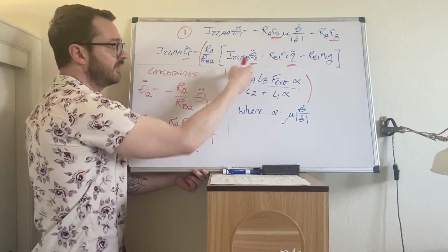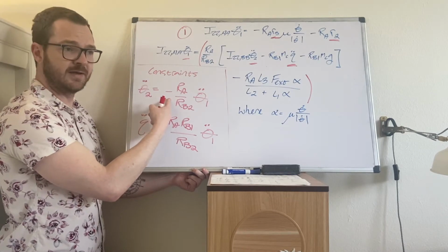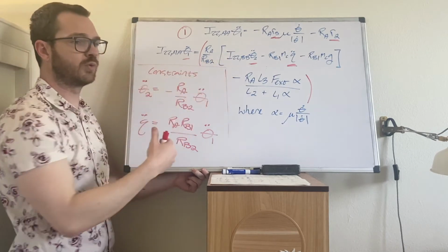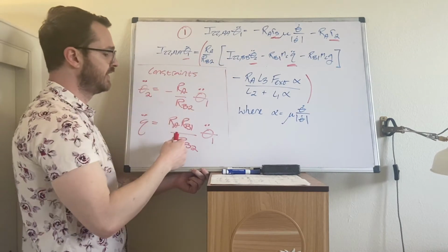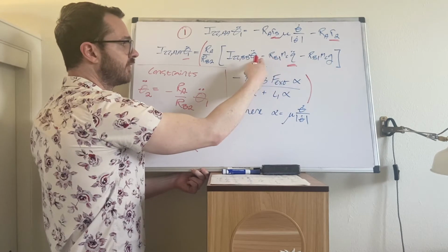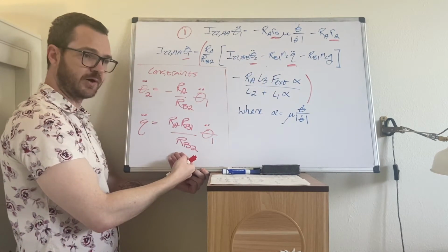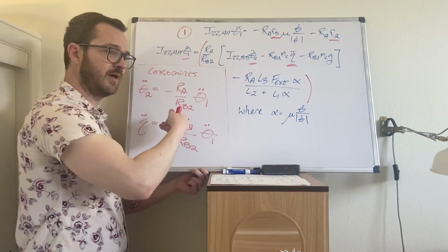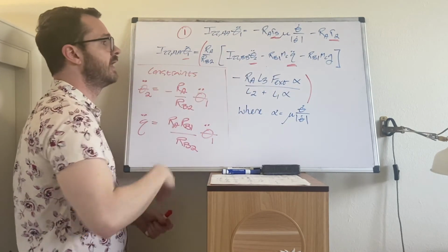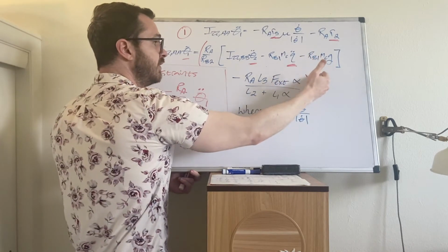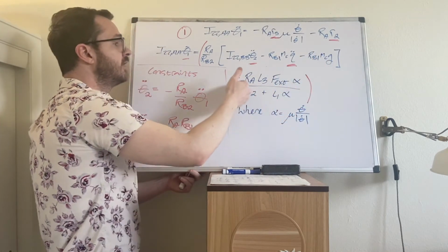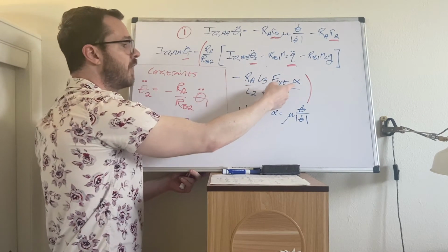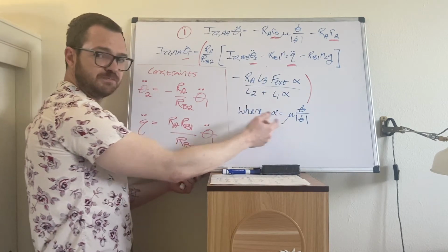Well, right now it's positive, and once we use the constraint, it's negative, which means you move it to the other side and it's positive again. So these two components are going to add. Next, the Q double dot term, it's already negative. We have our constraint sorted out. You're going to have theta 1 double dot in this term. You move it to the other side. It's negative, it becomes positive. Everything else on the right-hand side is going to be the weight of the block, and then also this effect of the external force modified by the friction term.